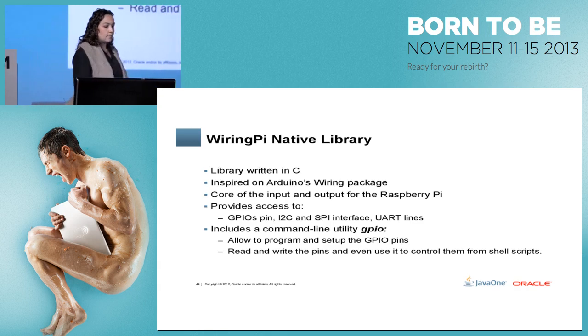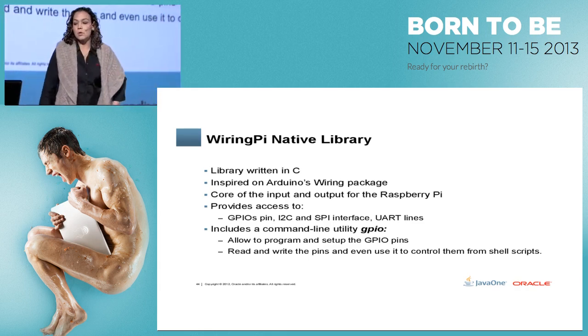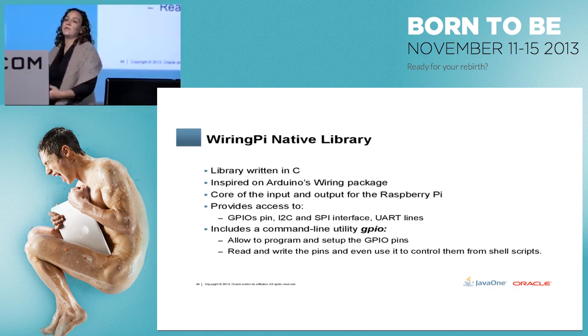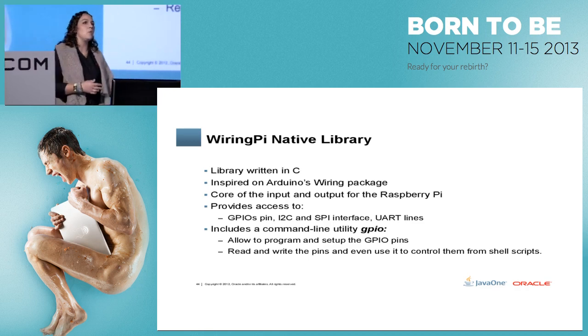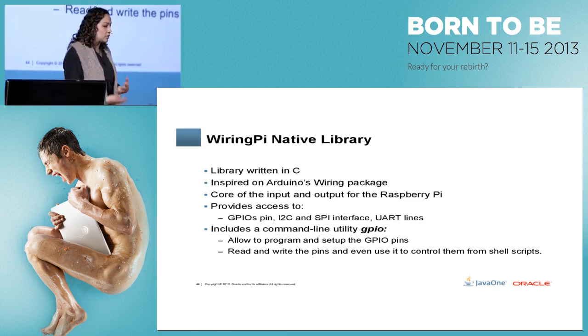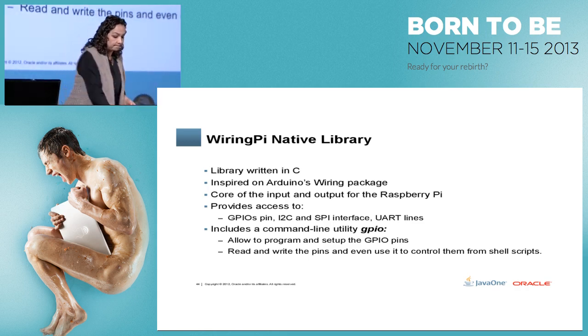It has a command line utility that you can actually use. So it actually allows you to really program the GPIO lines. You can define if you're using the lines for input, output, both, or if you're going to listen for the falling edge, or you do all the configuration for the communication.